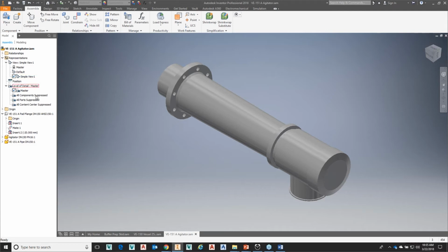Okay. So I'm going to work with that, and basically anything that's excluded, like that flange, will not be part of my simplified part. Now, the next step, I want to define envelopes. So most of these parts are simple enough that I can replace them with a bounding box or a bounding cylinder. So that's what define envelopes does.